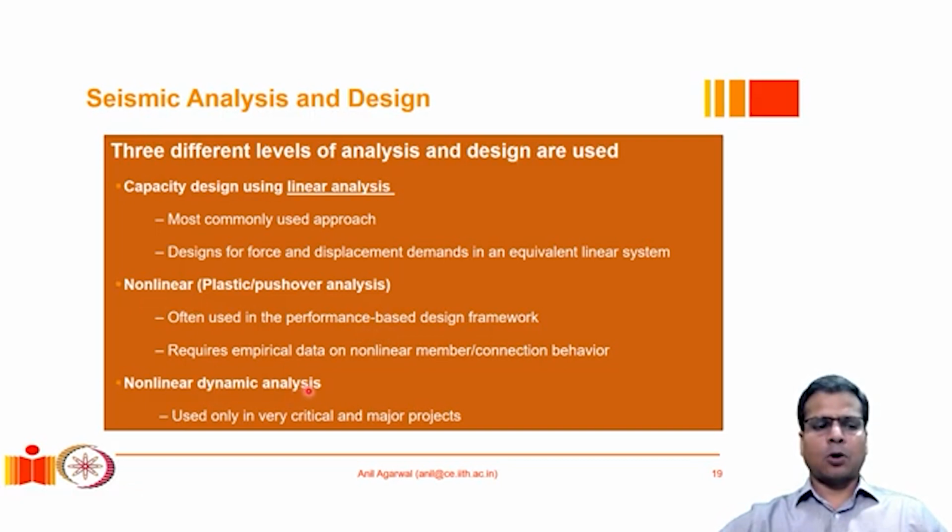The third and the most complex one is known as nonlinear dynamic analysis. In the second one, even though we were accounting for the plasticization of the structure, we were not really accurately accounting for the dynamic aspect, the time variable aspect of the earthquake. So in a pushover analysis, we keep pushing in one direction in a monotonic way, which tends to simulate the most severe earthquake, but does not really simulate the earthquake properly.